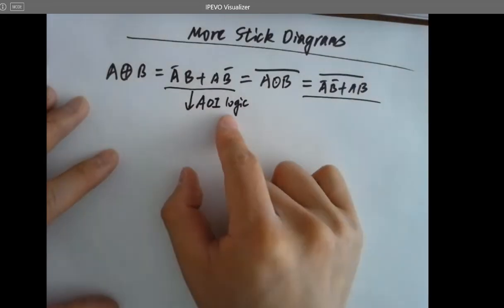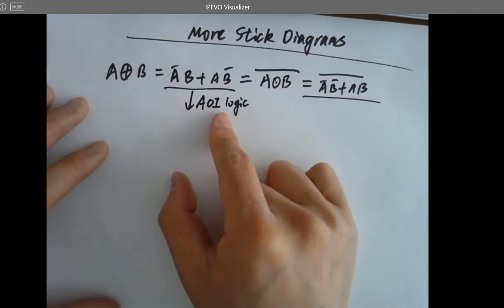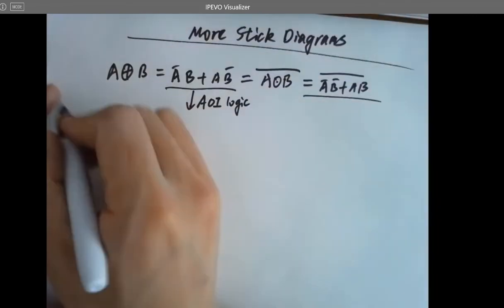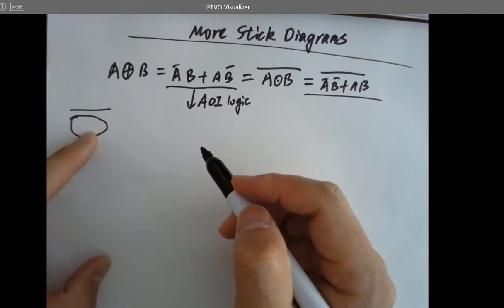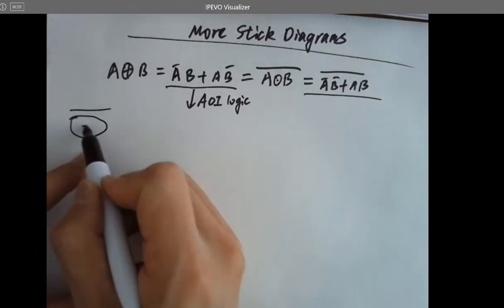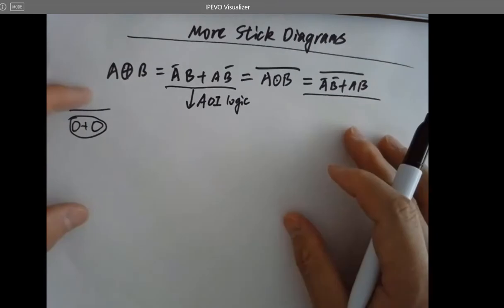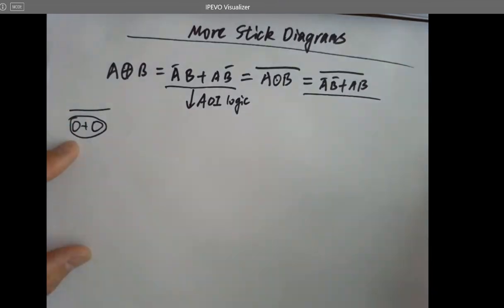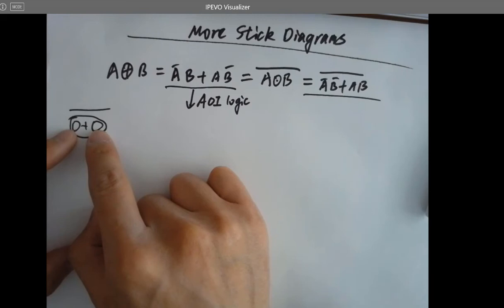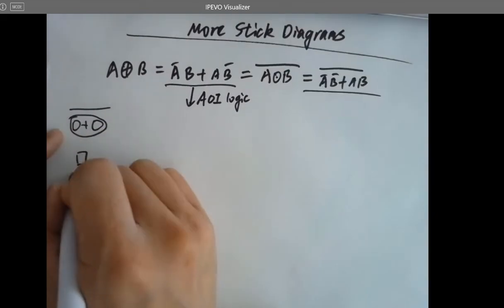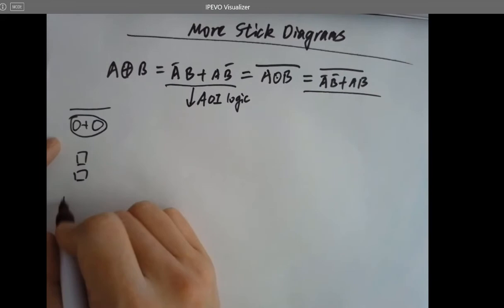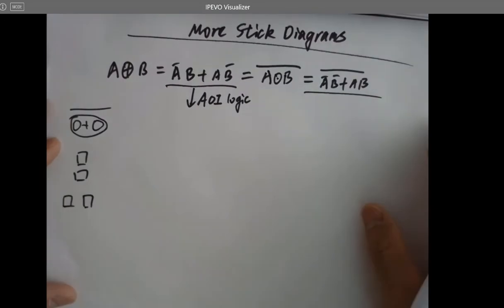So everything has to be underneath the bar. Then you can apply the rules: if you have an OR logic underneath the bar, you are going to treat this guy as a NOR gate. So the PMOS are in series on the top and NMOSes are in parallel at the bottom.